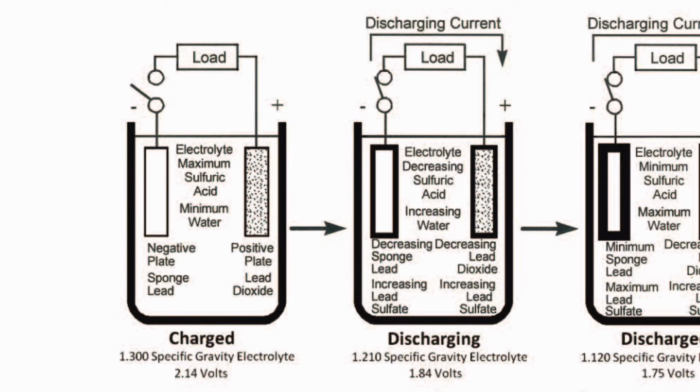All loads total to just over 360 amps. Allowing 24 hours for battery recharge, an additional 361 amps divided by 24 hours, or 15 amps, is needed. So the total available current needed on the 48-volt bus is 361 amps plus 15 amps, or 376 amps.